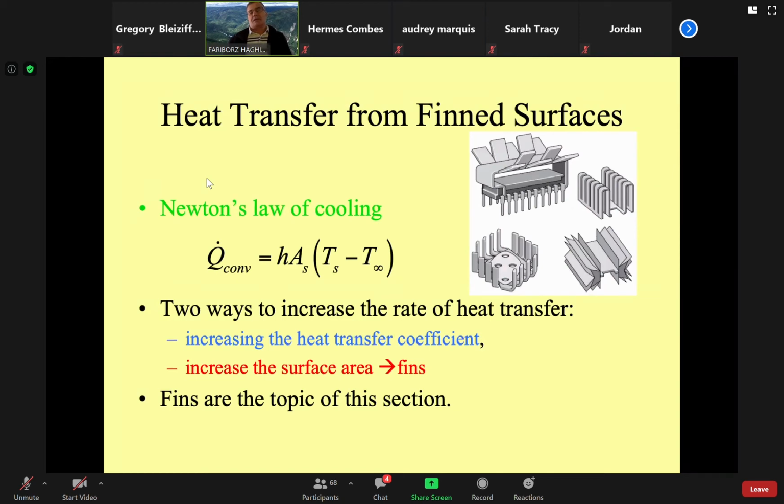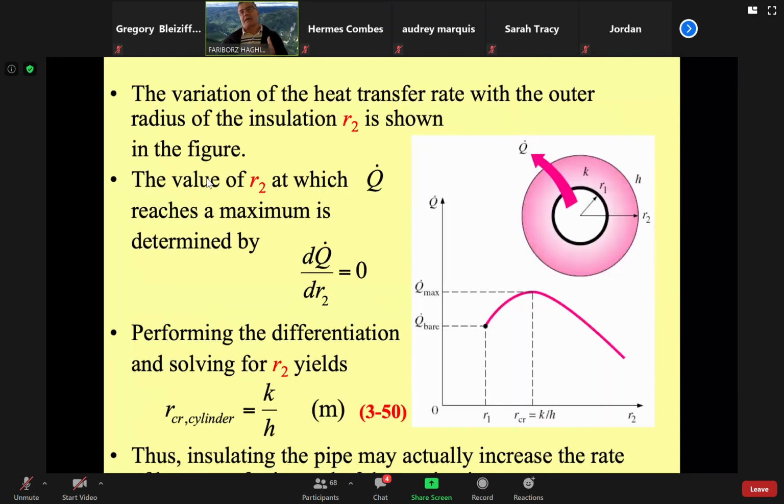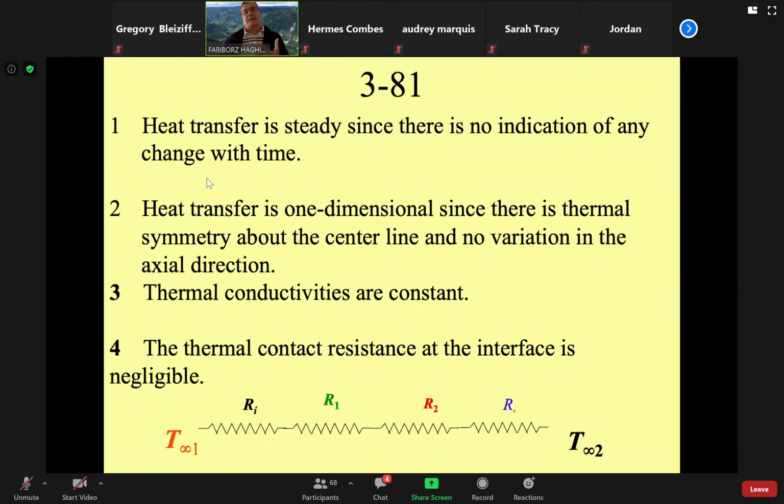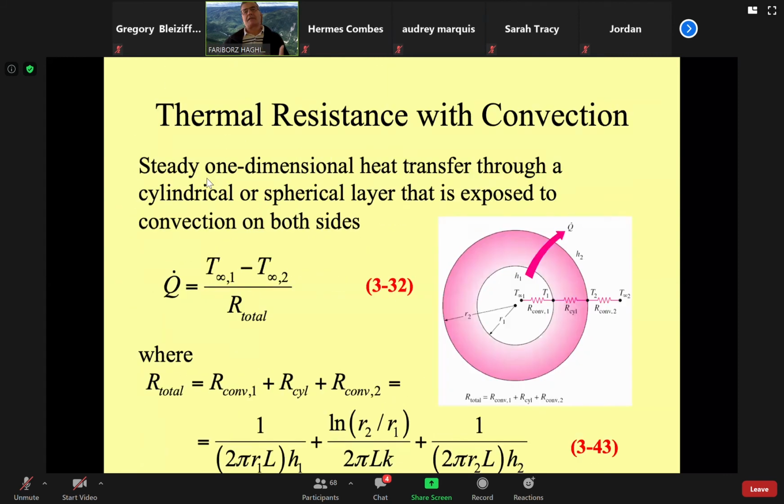Now, any question? Again, let me go back and see how we define the value of the thickness of insulation. You can see you have a convection here and the conduction here, and when we define a resistance here, we have to keep in mind there are 2 points we have to remember. The area for convection will change from inside to outside. You have to keep track of that, R1, R2. And also, this is the definition of resistance in cylindrical coordinates, okay?